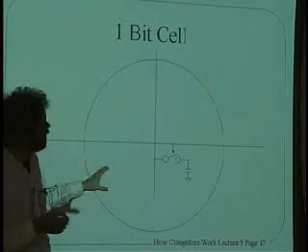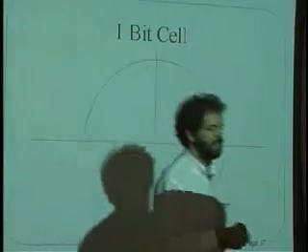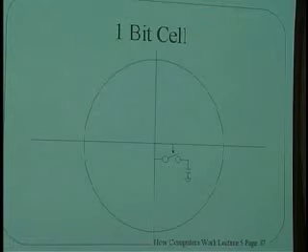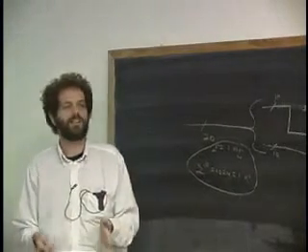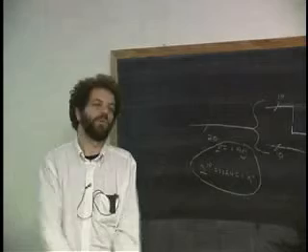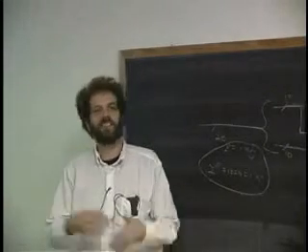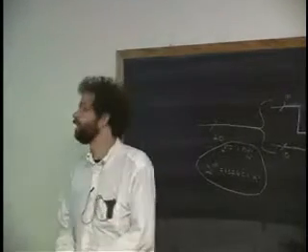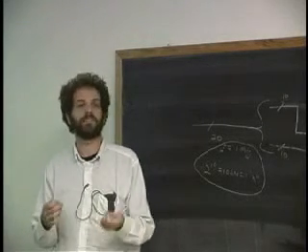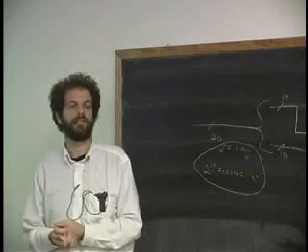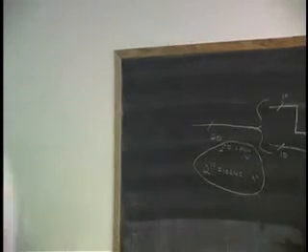The guarantee that they give, usually with these chips, is that the storage on these little plates, which serve as little bathtubs to hold charge, is leak-free on the order of a 1,000th of a second. Just like if you fill up your tub, even if it's a leaky tub, and you come back a second later, it's not that all the water is going to be gone. It takes an hour for the water to slowly leak down. So with these typical devices, the time constant is on the order of a millisecond, but you can depend that the charge will still be there. And we'll talk about what that means.